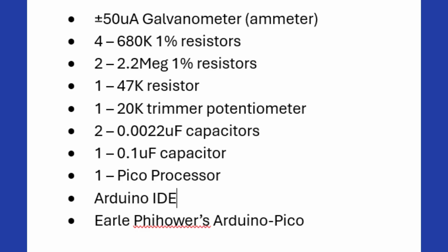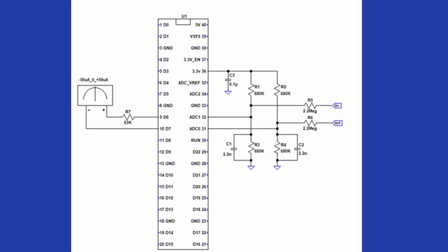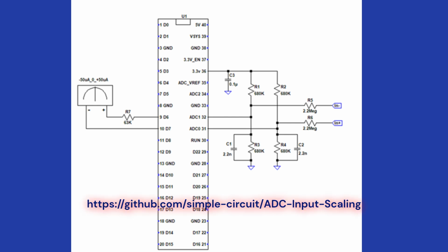Here are some things you will need. Test equipment such as a DVM and variable DC power supply are required for calibration. The ADC uses a differential input. The common mode voltage and range is plus and minus 10 volts. The minus input can be grounded.